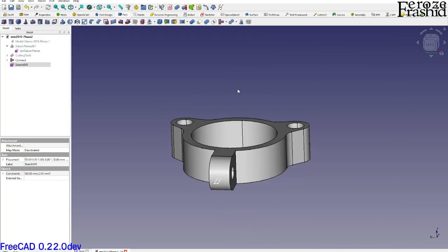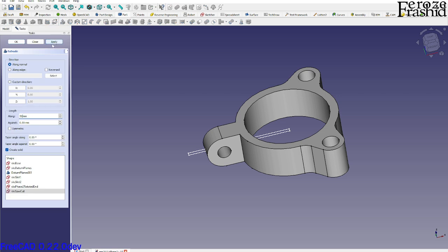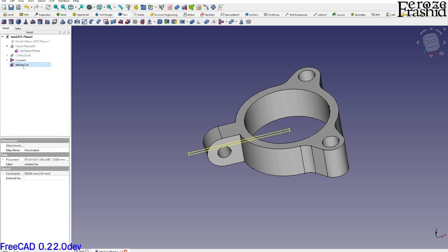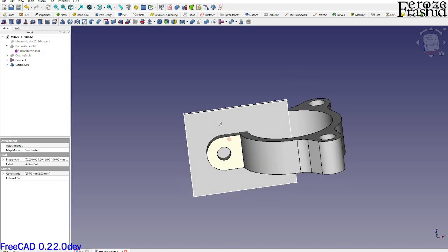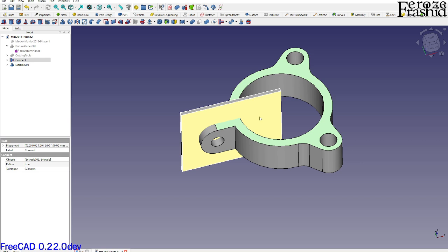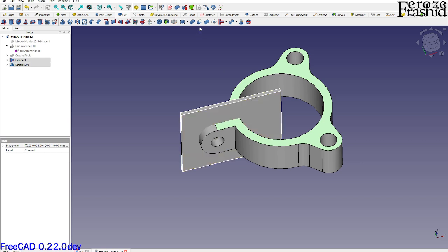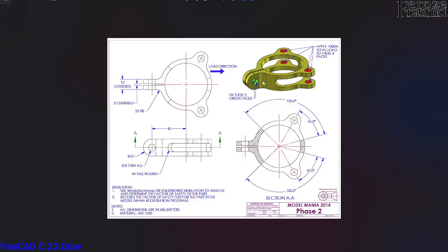All right, now this is a saw cut, so it will go up and down. Let's say get saw cut and extrude that for, say, I don't know, extrude that for 50, I guess. Okay, make it symmetric, and all it matters is that it should go up and down, covering the cut that will be performing on the object. So take this object and take the saw cut, make a boolean cut. So there it is. That is exactly what we are looking for.